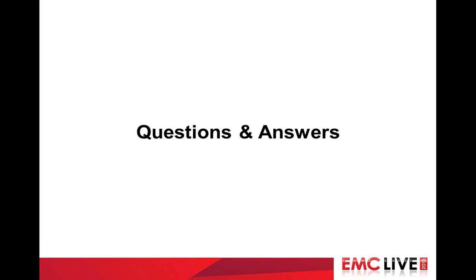The first question I have for George is, is the multi-tone testing system over-testing the EUT? The short answer, Carl, is yes. You are exposing the EUT to more energy than you would with a single-tone environment. However, it's probably a more real-world test, and the standard does not say that you cannot overexpose your EUT as long as you define a failure as a single-tone event. Okay.